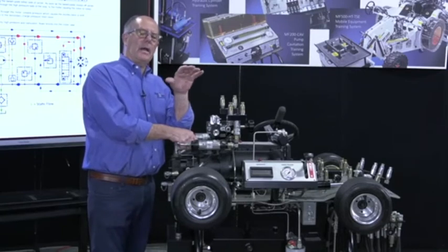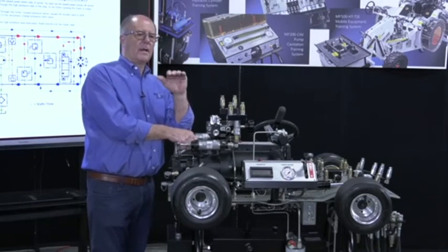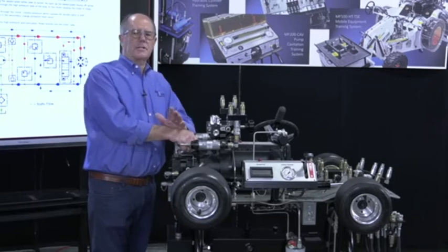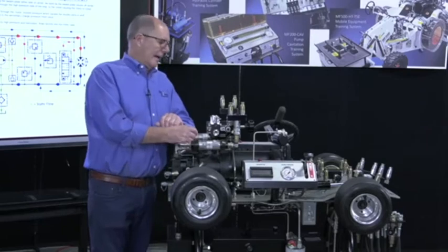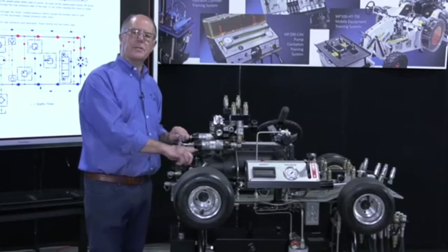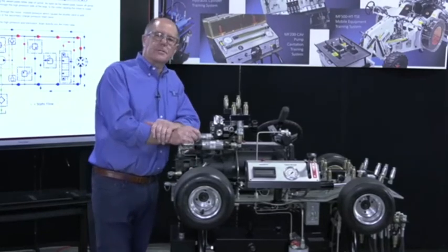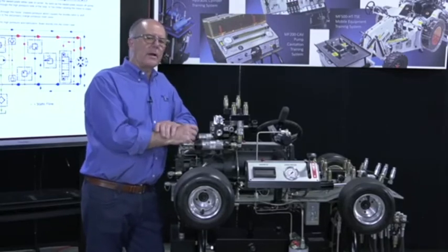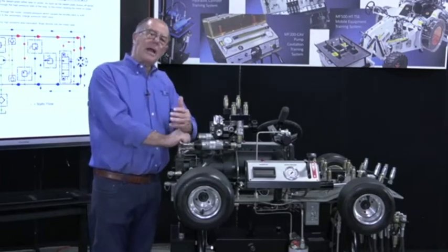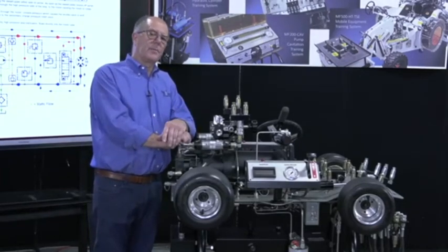I would highly recommend that instructors advise students that when a manufacturer says, and many do unfortunately, disassemble and inspect in the field. How many students, or technicians, are actually trained to disassemble and inspect anything? And then you say, well, disassemble and inspect this valve here, this cross-port relief valve in this transmission. Well, fine, I can take it out, but I can't disassemble it. You can't take it apart. So what does disassemble and inspect amount to? We've got to be really careful about how we interpret that. Am I competent or qualified to do that? It's a whole different ball game.